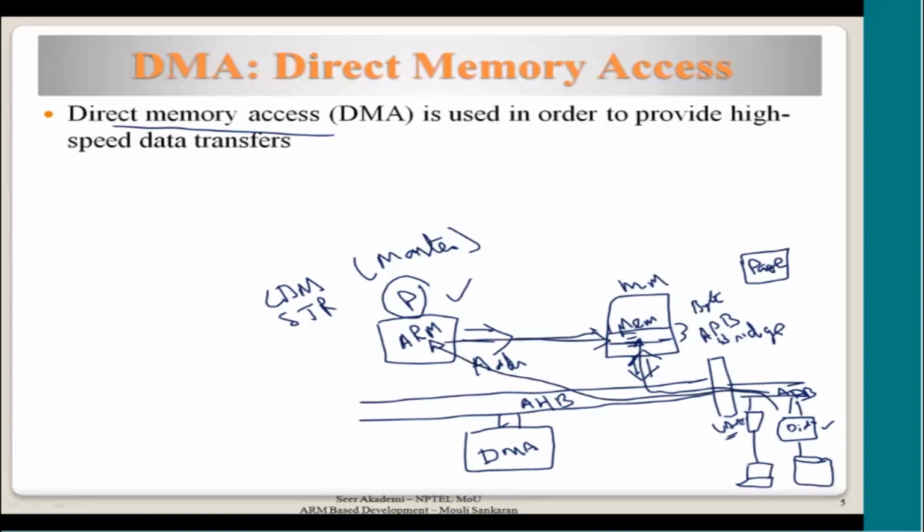So you can see that if you need to copy a character coming from a peripheral and write it into memory, the peripheral is a slave device, so it needs to be accessed by someone. It could be the processor. ARM can access the peripheral register because it is all mapped to memory, but you can't do a memory to memory transfer.